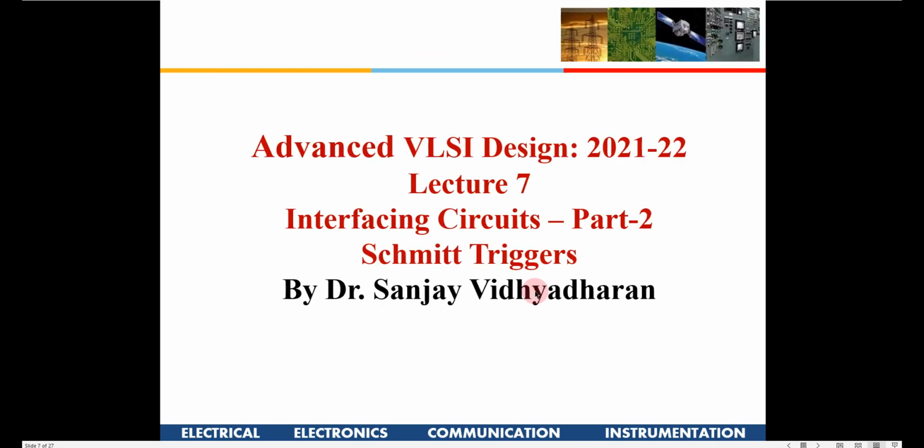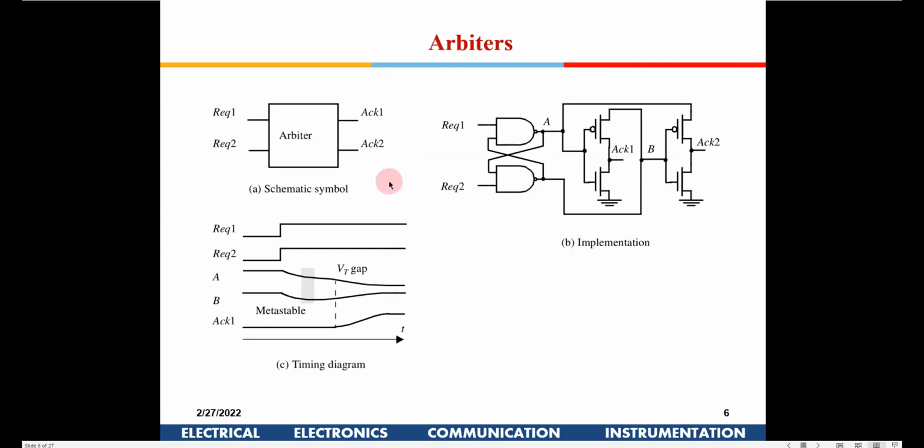No, this is not a self-timed circuit. Even in clocked circuits, there are request, acknowledgement and handshaking signals. Yeah, like you said, there will be handshaking signals in asynchronous circuits. Surely there has to be, even for synchronous systems also.